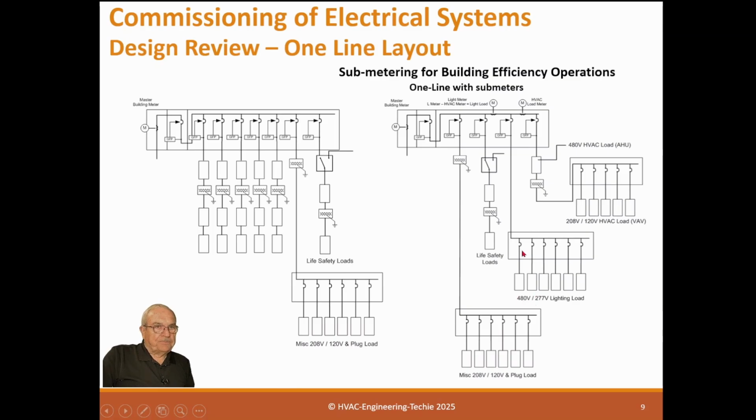Now, I say this in the design process video, that when I first started, HVAC was normally about 60% of the load, and lighting was about 2.5 watts a square foot, and plug load was below half a watt a square foot. Well, nowadays, that's all reversed. Lighting is down below half a watt, and plug load is way above 2.5 watts. Remember, plug load is anything you plug into a receptacle, including data center, data closets, your network infrastructure, all that sort of thing are all on plug load.